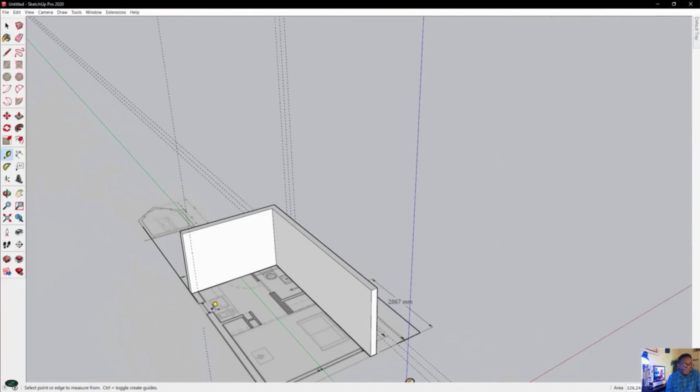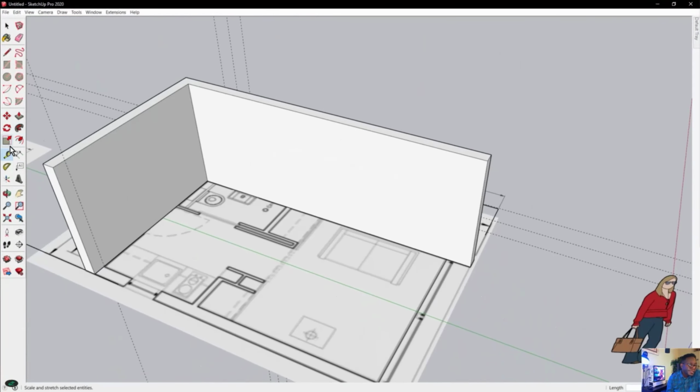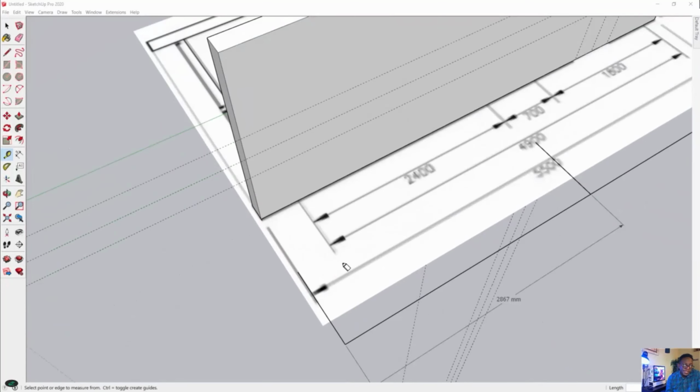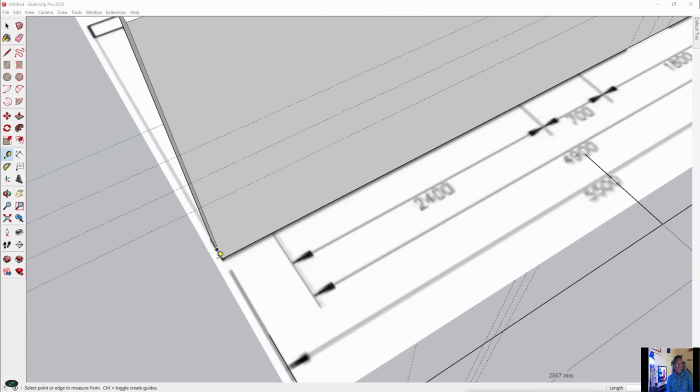So what we want to do is work out what this dimension would be here. And that would work out to be about 200, about 400 between that distance there. Including the units. So my units is set to architectural, so we're going to set that to engineering, and we're going to carry our decimal. So that's how we get that dash line there. No, we don't need any decimal. Now we can easily offset this line to this point.